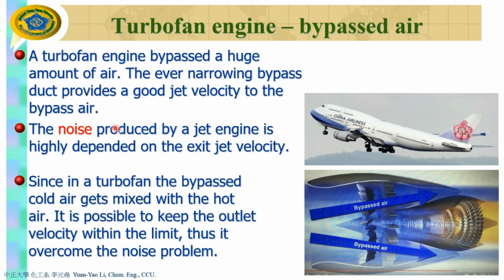The noise produced by the jet engine highly depends on the exit jet velocity. Since in the turbofan the bypass cool air gets mixed with the hot air, it's possible to keep the outlet velocity within a limit. Thus, it overcomes the noise problem.